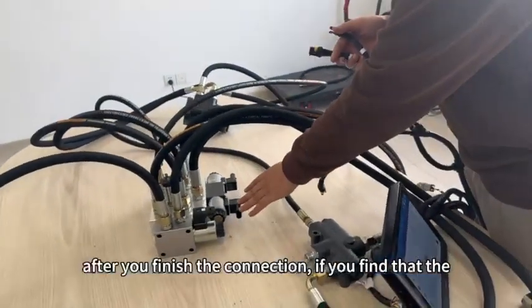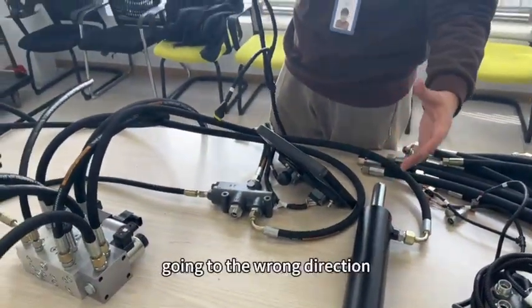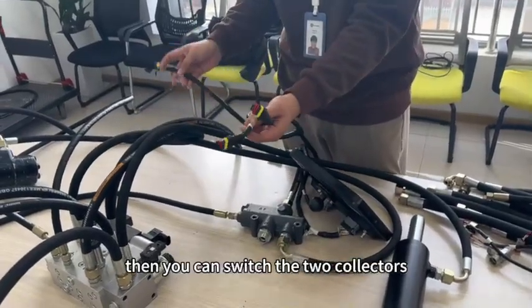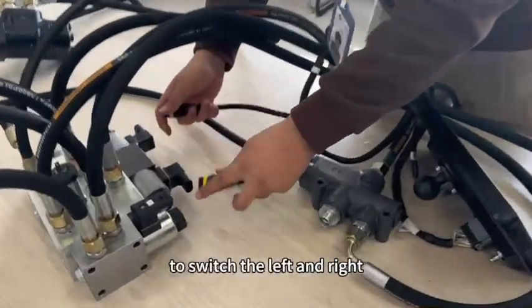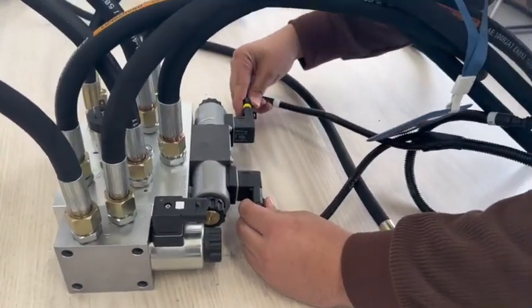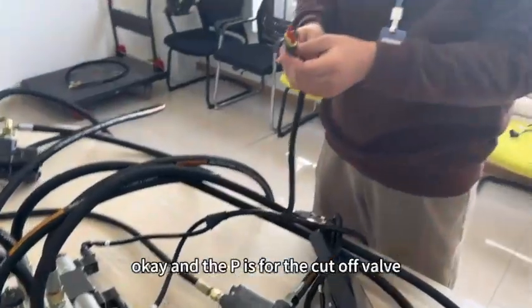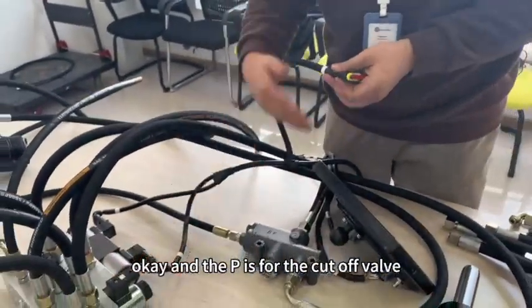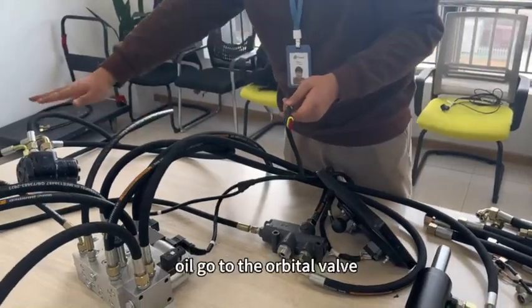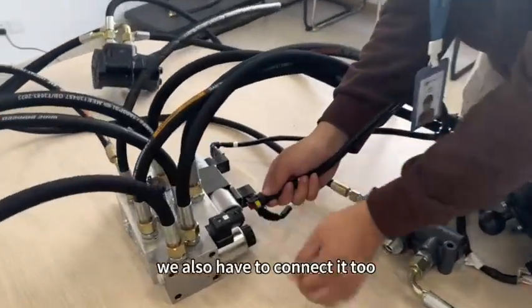After we finish the connection, if you find that the steering wheel is going in the wrong direction, then you can switch the two connectors to switch the left and right. Anyway, we will connect it to this one and this one. Okay, and the P is for the cutoff valve. The cutoff valve will make sure that when the system is in auto mode, no oil goes to the orbital valve. So the cutoff valve is very important. We also have to connect it.